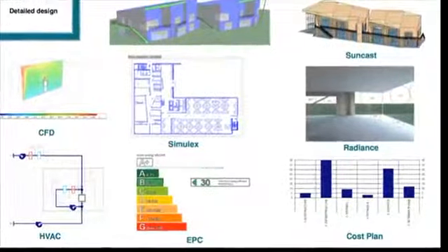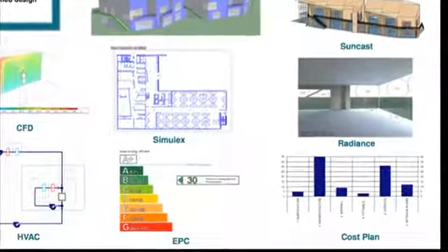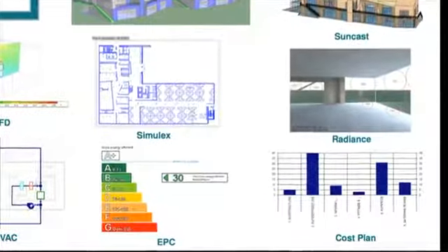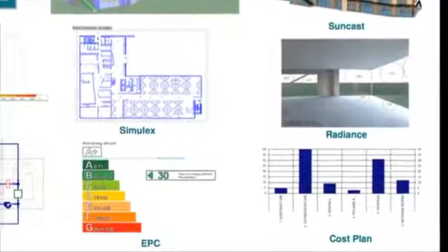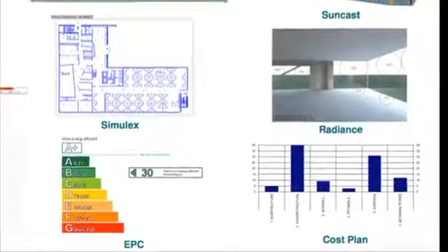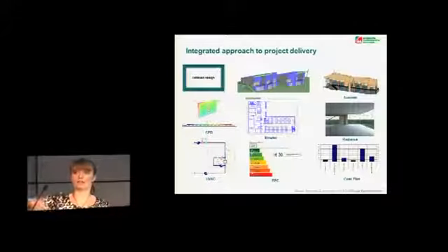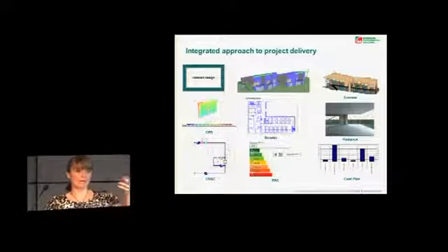But this introduces quite an interesting point in terms of the management of the BIM model. Because going through these slides here, it would look like it's just the same model that I'm taking in and then developing through those various stages. In reality, the workflow is more likely to be bringing a different BIM model in at different stages in the process. Okay, that's typically, so the architect will develop that and will be changing layouts and maybe changing shape and stuff like that of parts of the building, and then the engineer is bringing those new models across, if you like.